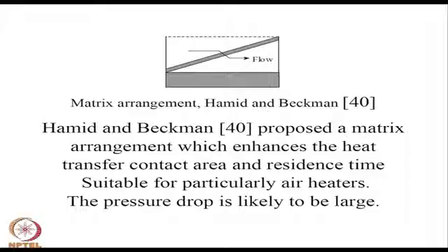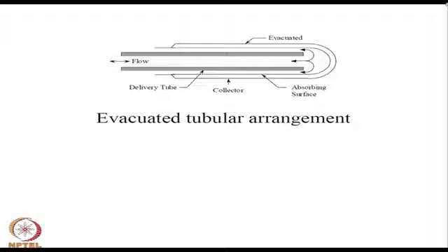The other way around is perhaps possible. You can increase the pressure drop and not gain the corresponding increase in heat transfer. So, that is like you can imagine a pipe, you put a plug at the end of it, the pressure drop will be enormous, but there will be no significant improvement in the heat transfer.